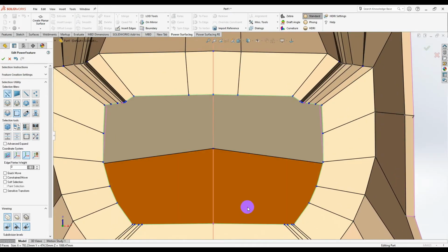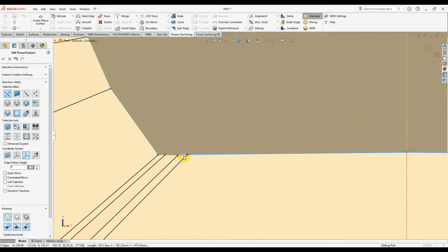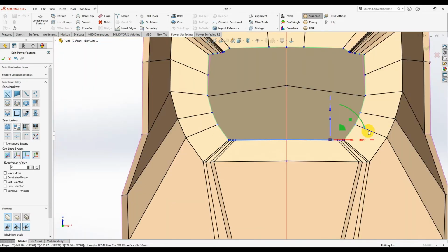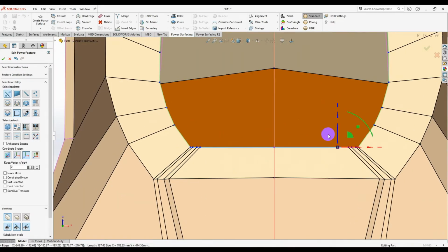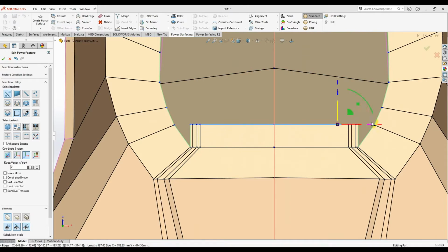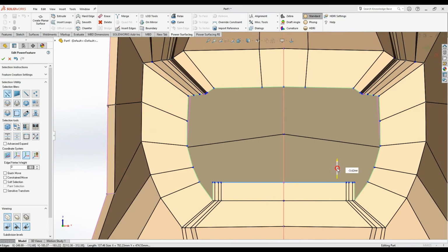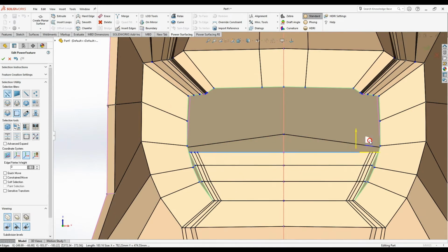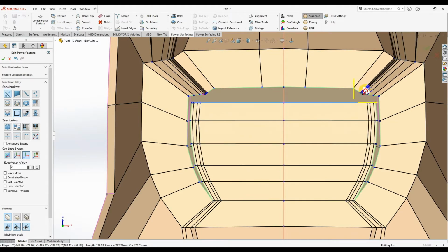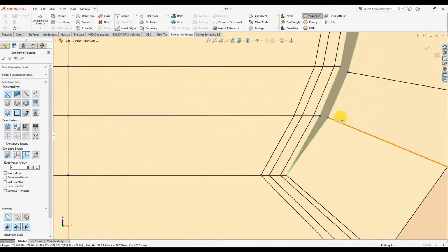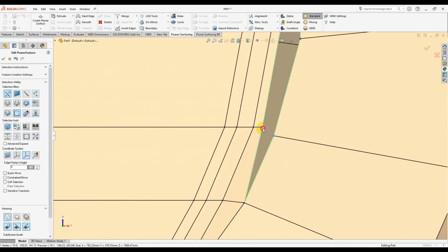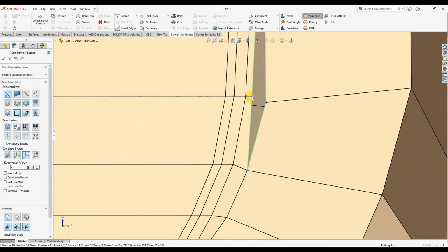And then I can close it manually by selecting this loop, and extrude to every single point at the other side. So this one goes to this one, extrude again and again and again until you have this shape. Now merging the lines, as you see, first point and second point, first point and the second point, to close them.